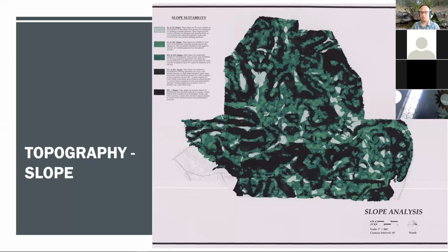Although I'll show you an example of some development in slopes greater than 25%. Soil stabilization and erosion controls may also be required to moderate steep slopes. If you want to develop on a steep slope, then you would need to treat the slope in a way, depending on the soil characteristics and soil stability and so on, just to make it nice and safe for development.